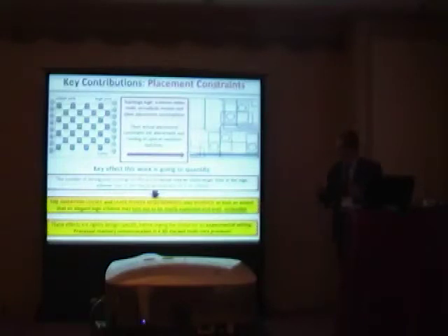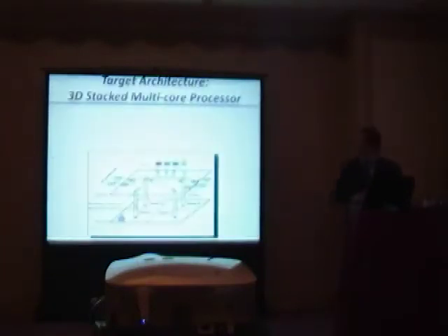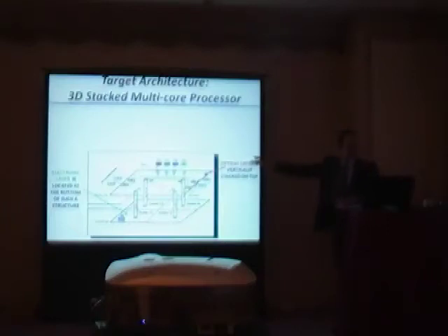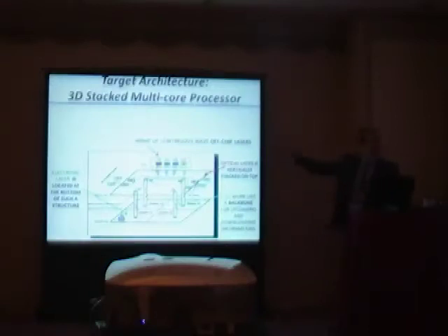In our case, we study processor memory communication in a 3D stacking approach. In fact, our target architecture is a 3-dimensional system, and it embeds an electronic layer which is located at the bottom of such a structure. Instead, we have an optical layer which is vertically stacked on the top of it. So we leverage TSVs because they work like a backbone for uploading and downloading information, and they also bridge these two important layers. In our work we also use an array of continuous wave lasers which are used to provide the optical power inside the optical layer.